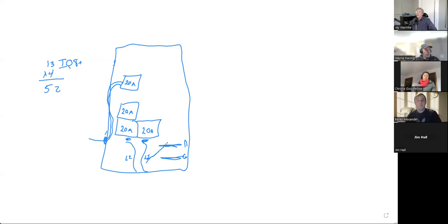And those are going to lead out as well. And then that's going to go to your AC disconnect. That's going to be your next stop. And the AC disconnect needs to be located within 10 feet of your meter, outside, well marked, externally operable. So that's all going to go into this AC disconnect.